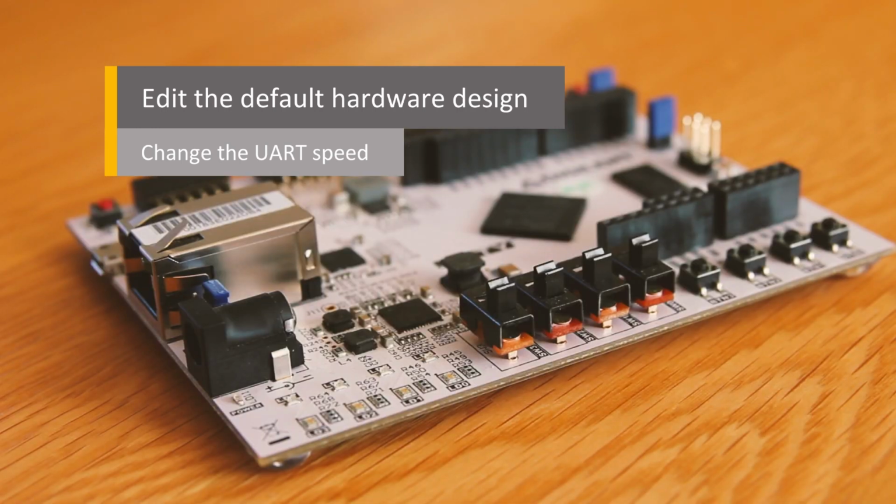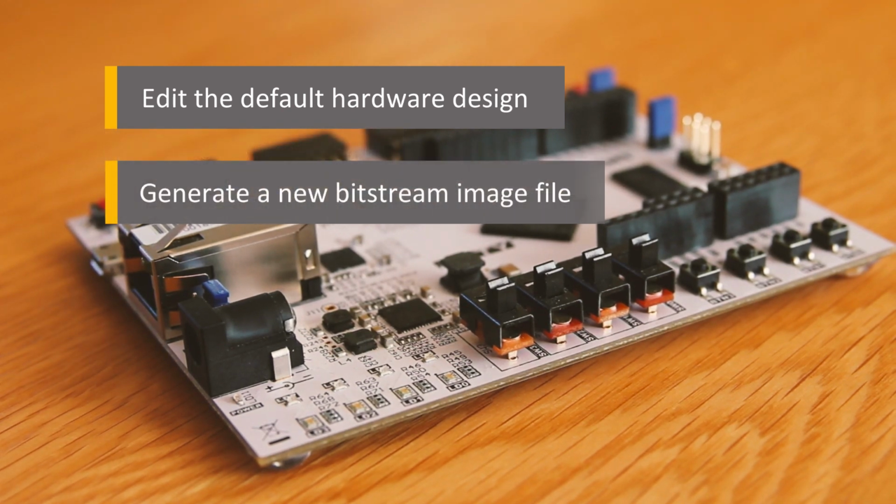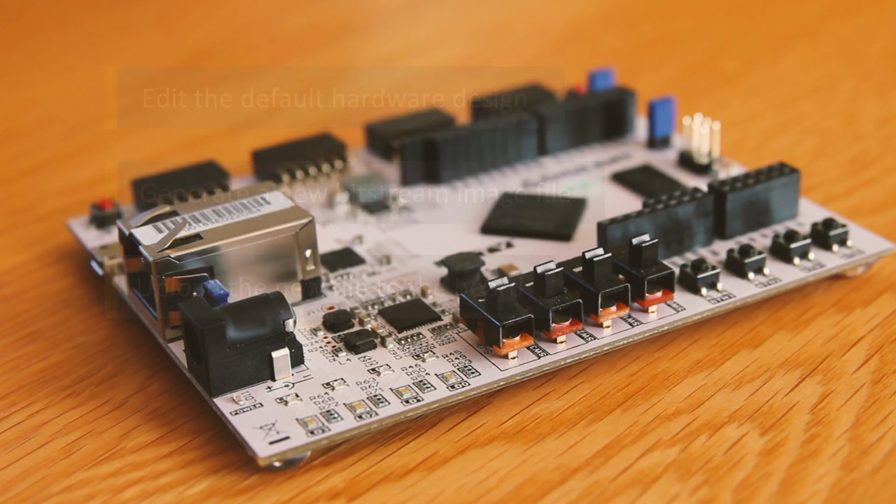Although it's unlikely that you'll want to change the UART speed in your own projects, it's this process of making changes to the hardware design, generating a new bitstream image, and uploading it to the board that you need to follow when you make your own hardware changes.